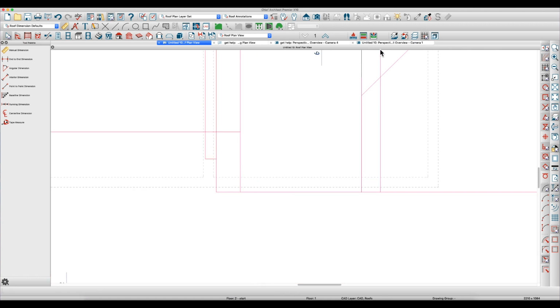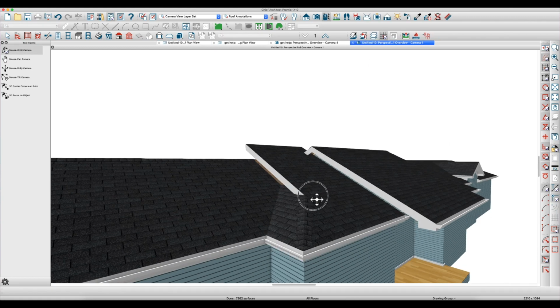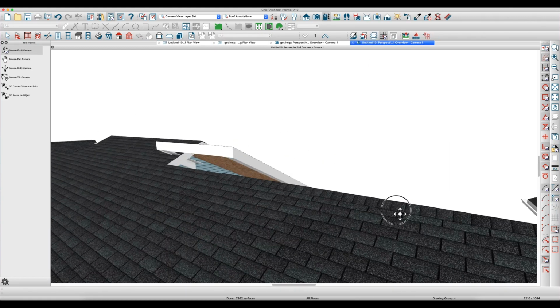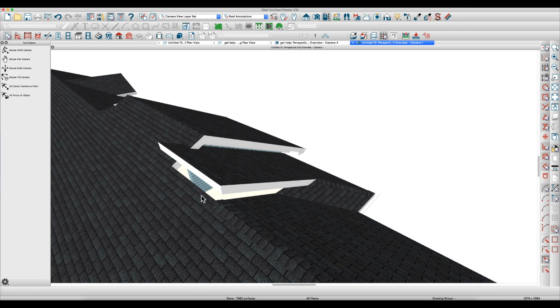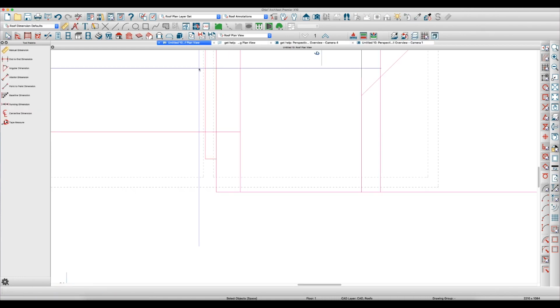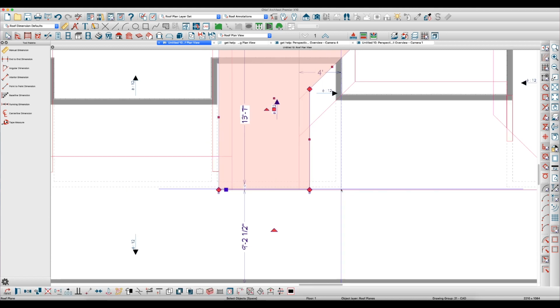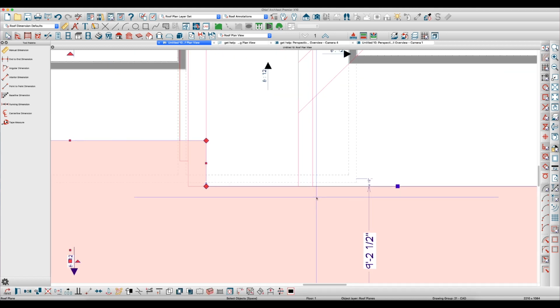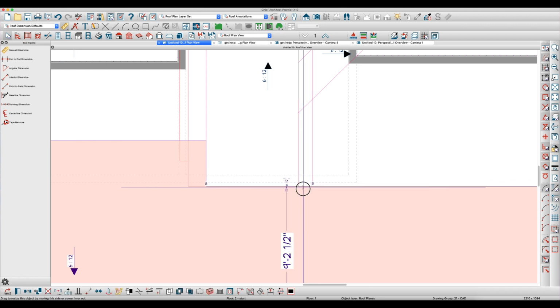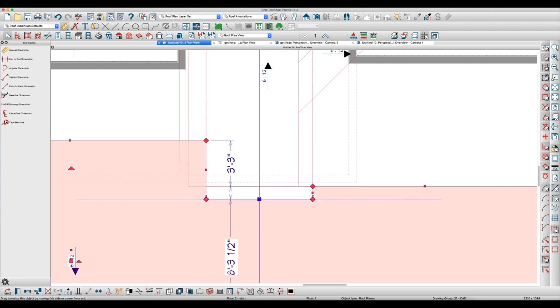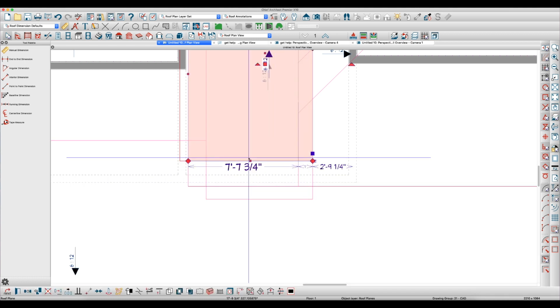Now let's take a look. There you go. Now this roof and this roof have to join. And see, this roof isn't joining properly. So we hit the 3 key, and right where they intersect, break it. And then what I would do is just pull this down, hit your 2 key, click on this edge, hit your 2 key, and hit that edge, and they don't move. Why didn't they move? Oh, it's this edge. I'm sorry. What is this?